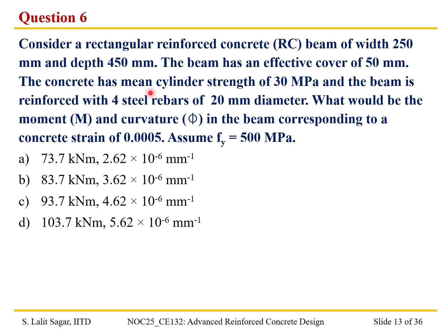Now the question is, considering the concrete strain of 0.005, what would be the moment and curvature corresponding to this concrete strain? Assume fy is equal to 500 MPa. Kindly try to solve this problem and let me know what would be the correct response.